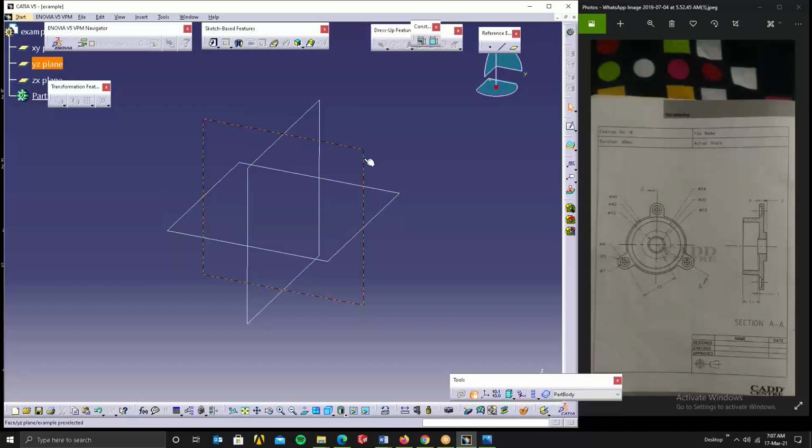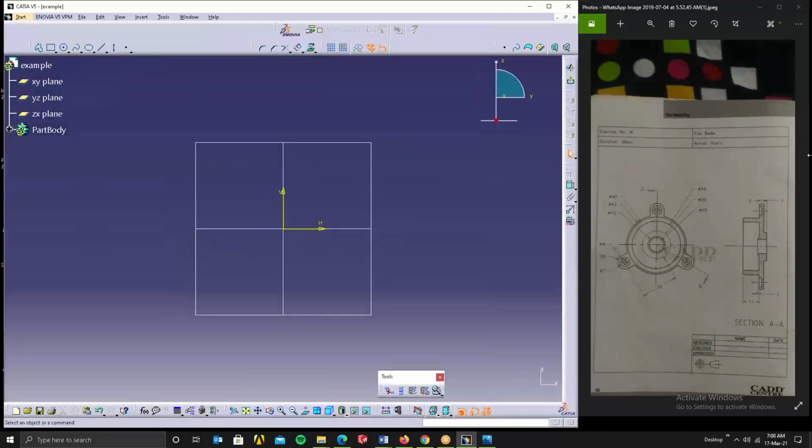So Srivardhan, we'll do this. I'll just select the plane first and go to sketch. Since Sri Prabha said these three things are popping out, we can't revolve this along with others. So we'll stick to only this. This circle is how much? 42.